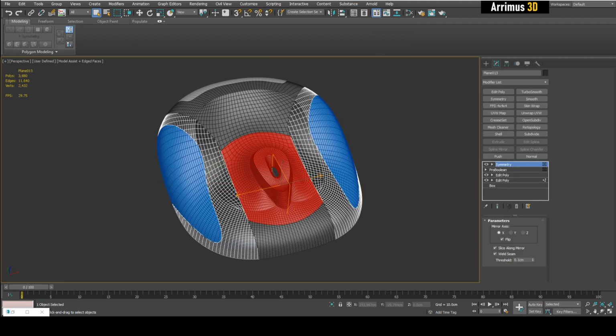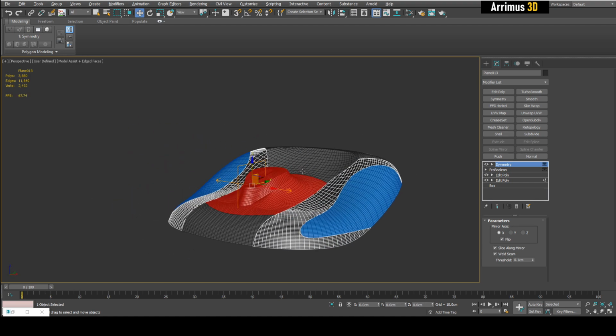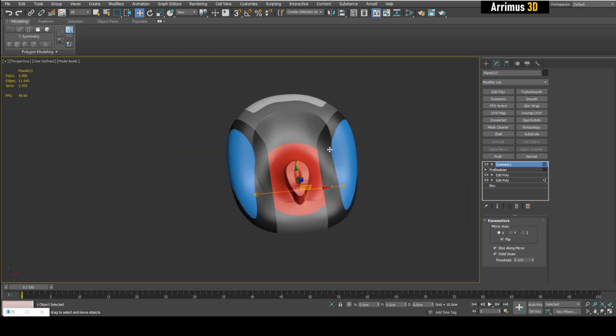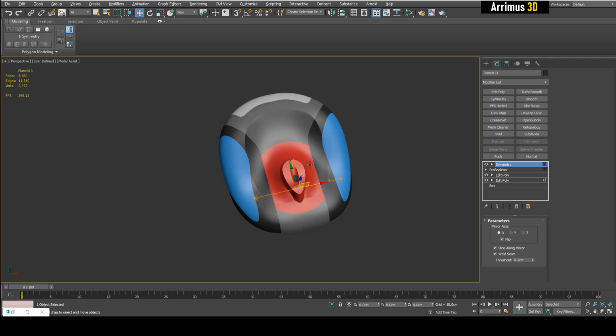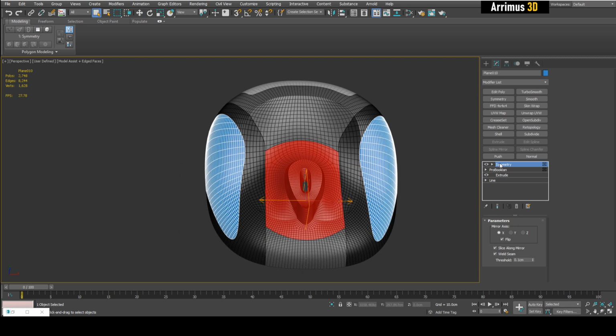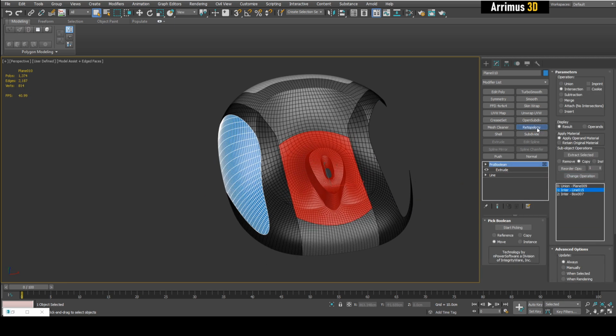But in this situation, I just want these panel lines to open up. Let's say this is like a hollow object and I just want these kind of panel lines. Well, now use a combination of freeform modeling and booleans, both spline booleans as well as geometric booleans to get this mesh that's ready for a nice retopology. So I'm going to delete symmetry beforehand just to make the process go faster and then retopology here.